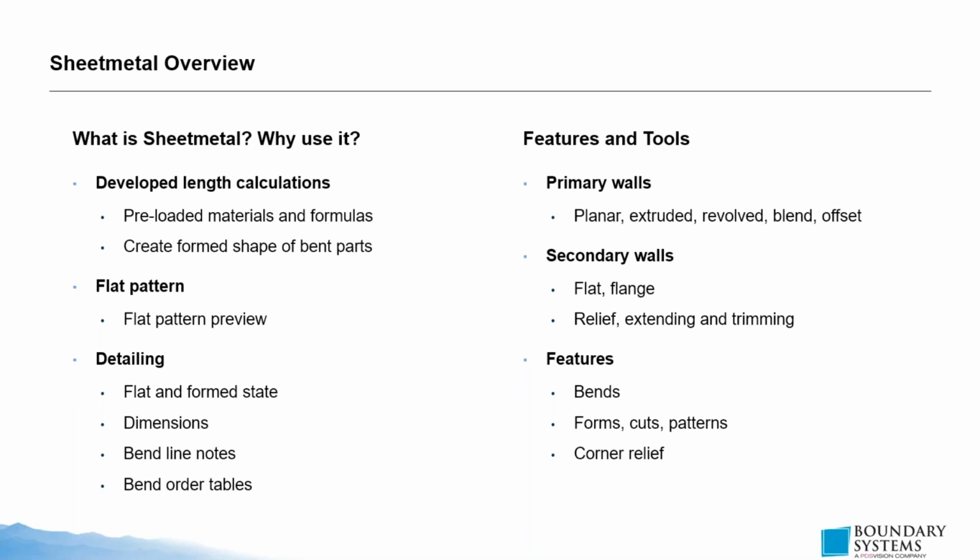These are once again going to be completely customizable, and that's actually going to be in the form of part files. So you can create your own forms by creating the 3D model of the punch itself and saving it as a part file. You can then load in that part file into your sheet metal parts and essentially simulate what it would be like to add that press to your sheet metal.